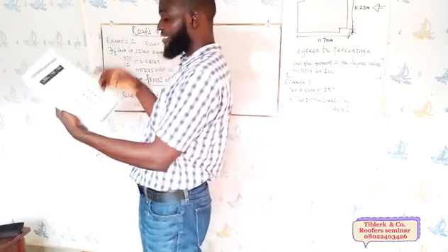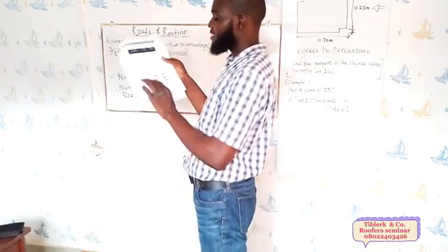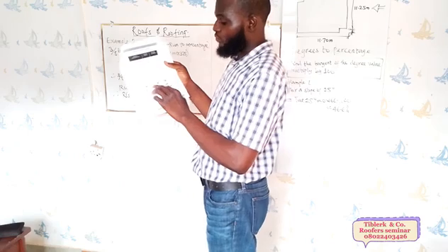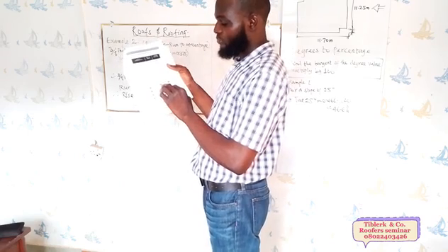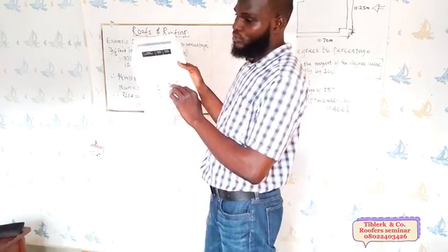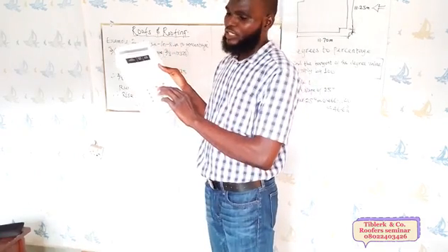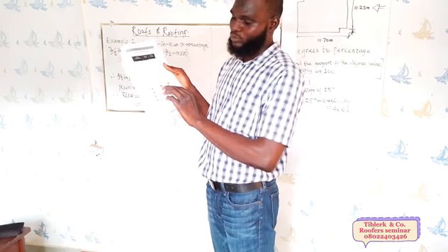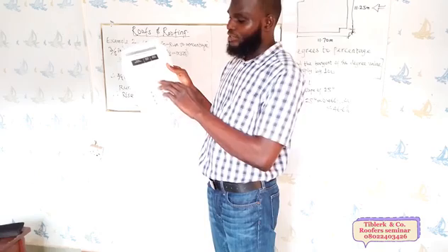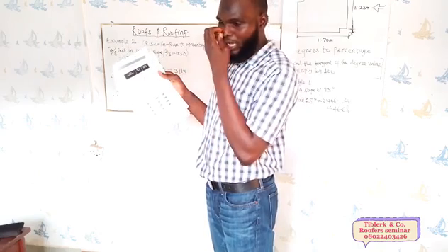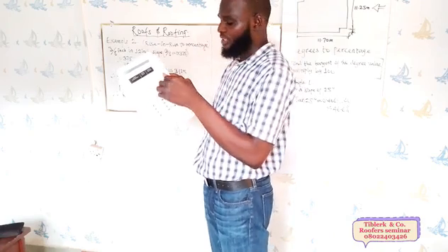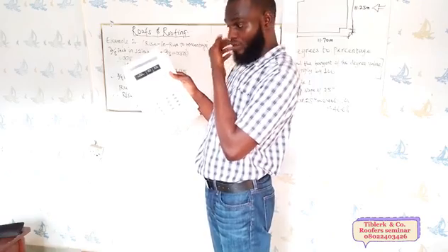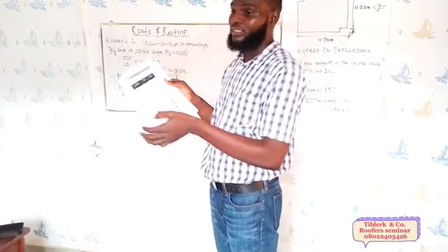So it starts from this 6 in 12. That is why it is highlighted and bolded. 6 in 12, which is 26.57 degrees. That is where the recommended pitch starts from. Not that you cannot use the lower one. Most especially when you are doing a flat roof, you can consider this 9.46 degrees or lesser, even the 2 degrees.